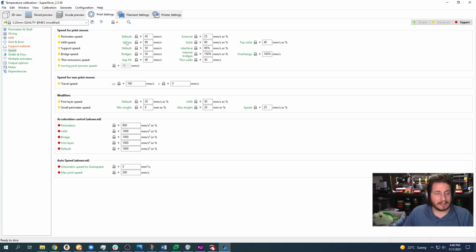Infill Speed, we've got a difference between our sparse and our solid. Now, understand, sparse does not mean little to no infill. It means anything that is not solid in this particular case. Sparse infill is what is used in industry. So I'm saying in the big boy 3D printers, the ones that cost like houses worth of money. They use the term sparse.